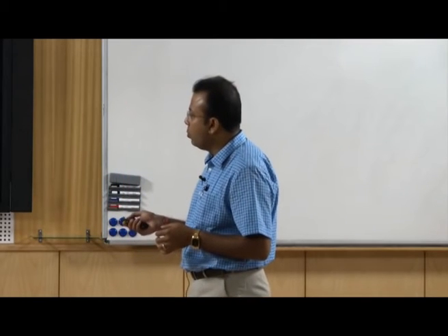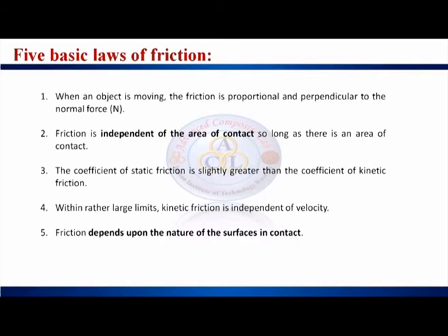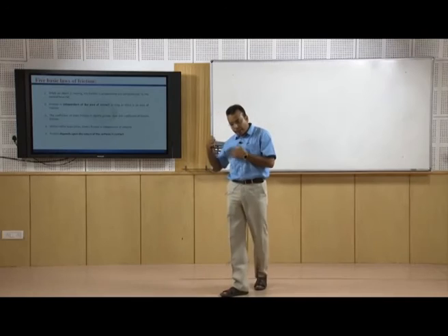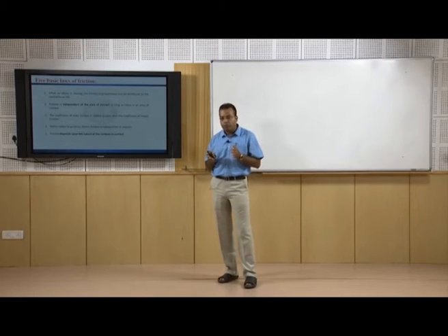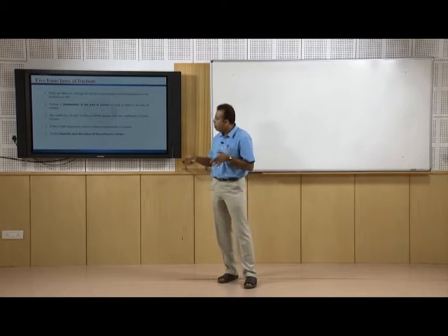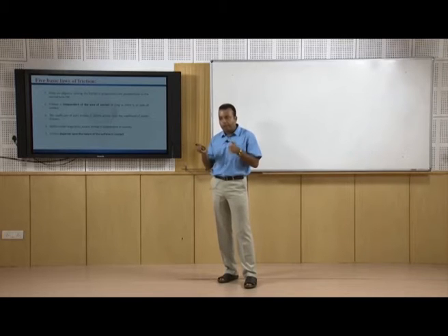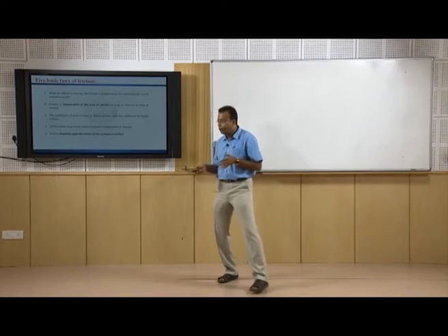The third is that the coefficient of static friction is slightly greater than the coefficient of kinetic friction, and the fourth is that, within rather large limits, kinetic friction is independent of velocity, and the fifth is that friction depends upon the nature of the surfaces in contact. In the subsequent slides, when we go deeper into tribology, we will discuss all the 5 basic laws.